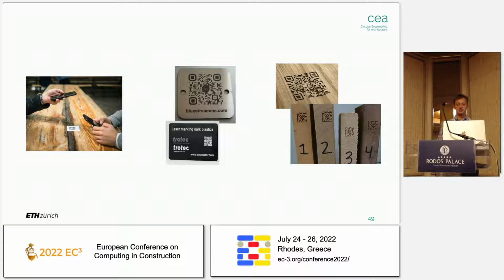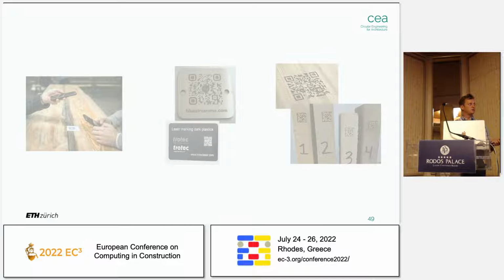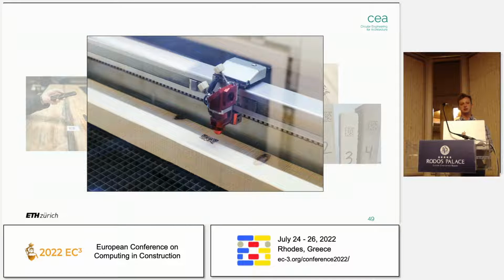The third approach we looked at was laser engraving. And the advantage of laser engraving is that it is embedded into the material, so you don't have to worry about the tag or the tracking technology falling off. But some of the disadvantages of engraving are if you modify the material in the future, such as a really thick layer of paint over the QR code, which could affect it. Ultimately, the solution that we looked into was the engraving of the QR code. This we found wasn't explored too much in literature or in practice yet, but we know it is also transferable to steel beams as well.